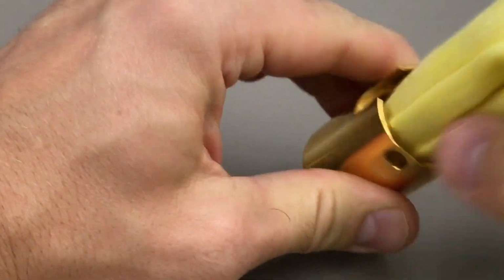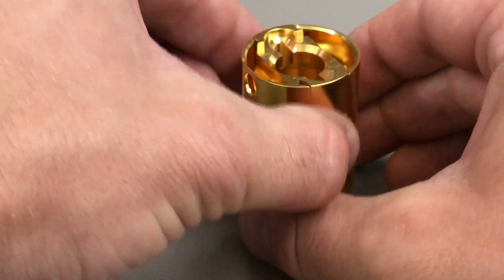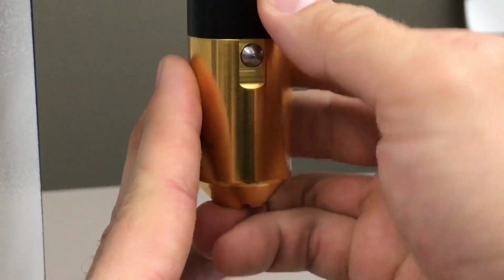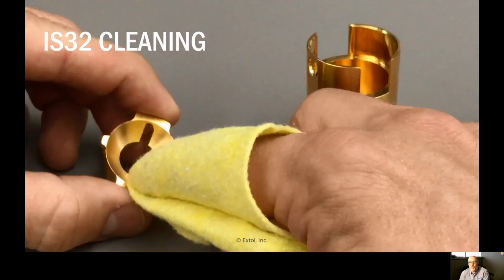It is important to note that these are gold-plated parts, so you don't want to go in there with a brush or with something like that. That red rag that every maintenance guy carries around that's got metal flakes and who knows whatever in it, please don't go after it with that. Generally what I tell customers is that if you treat this like your eyeglasses, you'll never have a problem. You don't want to scratch it up.